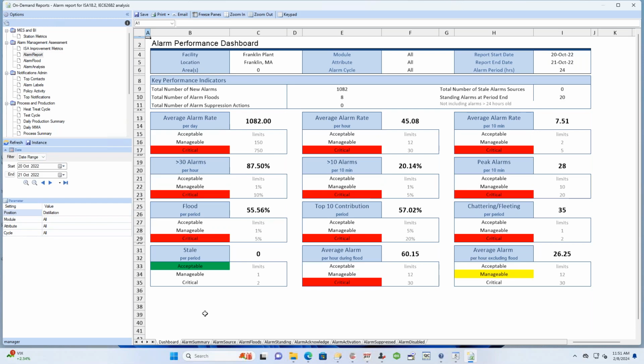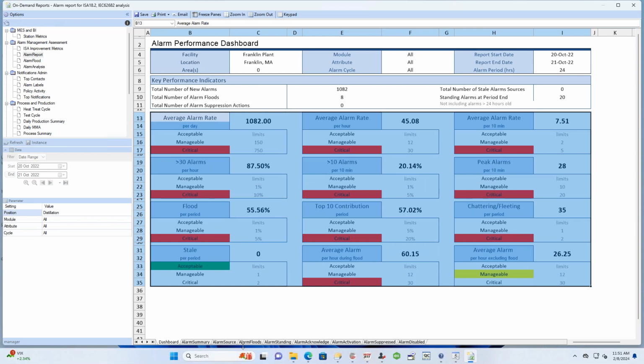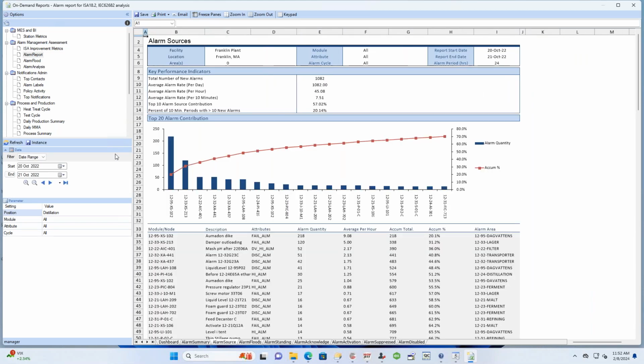So this also allows us to target particular production lines, areas, and operator positions, and perform the ISA rationalization loop from that person's specific perspective. Now, the end goal of doing all this is to make improvements and be able to tell that you are making an improvement over time. And so we have built that layer into the solution. As these reports are running automatically, these scores and the top 10 alarms are also being trended historically, so we can see how they're changing over time.